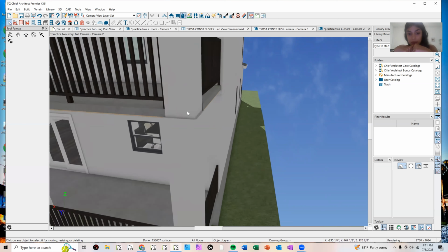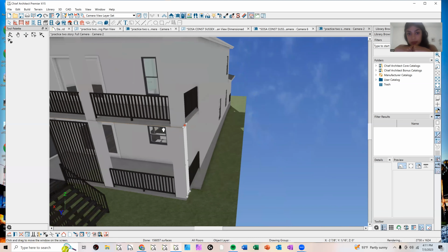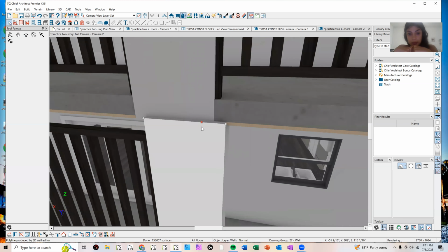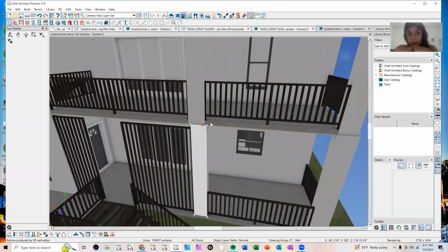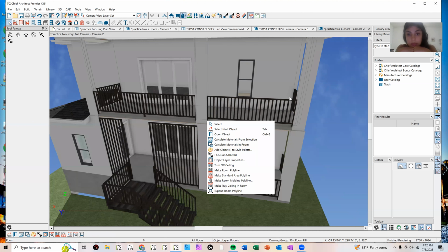But a lot of times you do run into little issues like all these here. You'll run into that a lot because for some reason the program will offset when you're using walls. That's why if you dissect one of my plans, a lot of times I'm doing everything with polygon solids because I can control and move them myself. The walls just say, this is where I'm putting the wall, and it won't let you bend it or do anything with it.